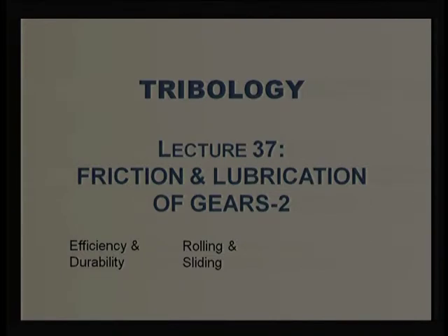When the pressure is more than a gigapascal, there will naturally be thickening of the grease or liquid lubricant, whichever we are using. That thickening converts semi-solid to almost solid and liquid to semi-solid. In addition, there will be elastic deformation. That is why we say elastohydrodynamic lubrication mechanism.